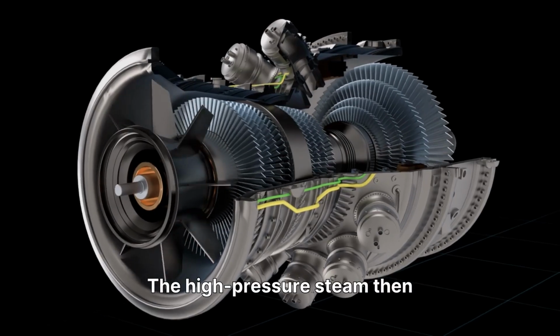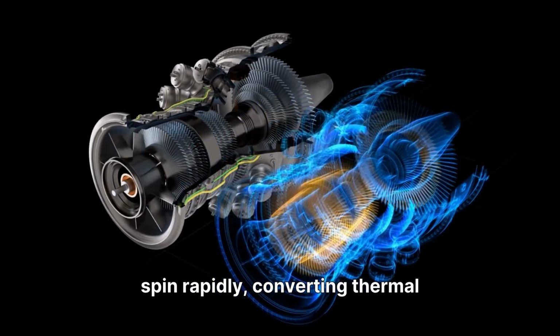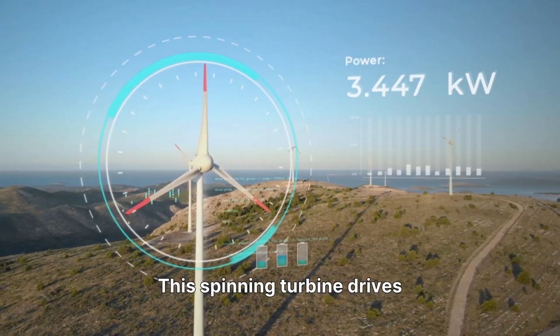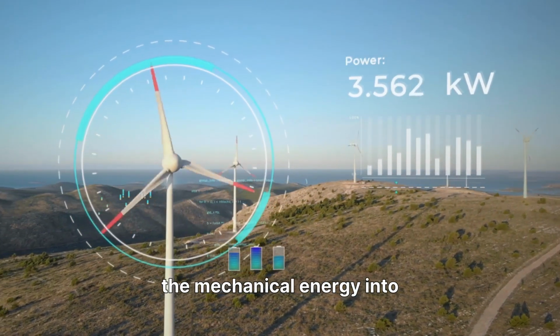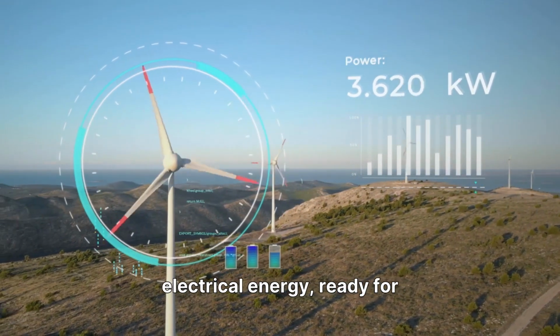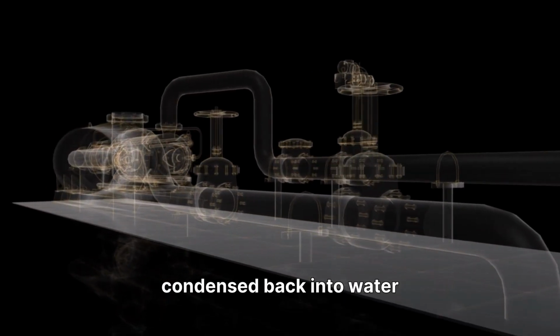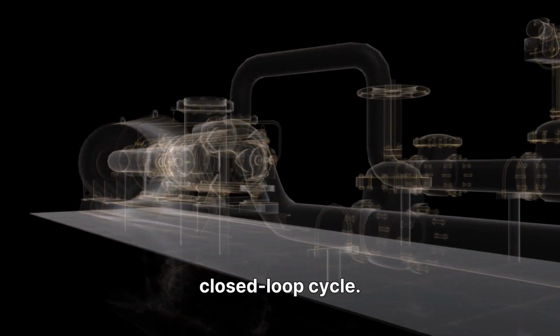The high-pressure steam then rushes to the turbine blades, causing them to spin rapidly, converting thermal energy into mechanical energy. This spinning turbine drives the generator, which converts the mechanical energy into electrical energy, ready for distribution. Finally, the steam is condensed back into water and recirculated to the steam generator, completing the closed-loop cycle.